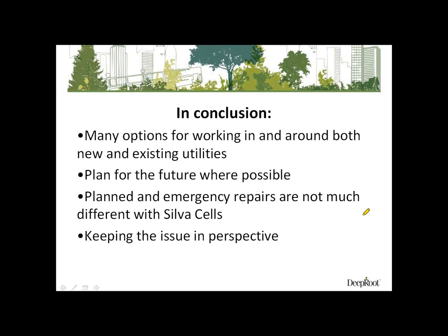So instead of just having the green area or the rain garden area where the trees are planted as your only green area, that's what it looks like from the surface, but it's actually Silva Cells for stormwater retention and soil volume underneath the adjacent sidewalk and hard surface.